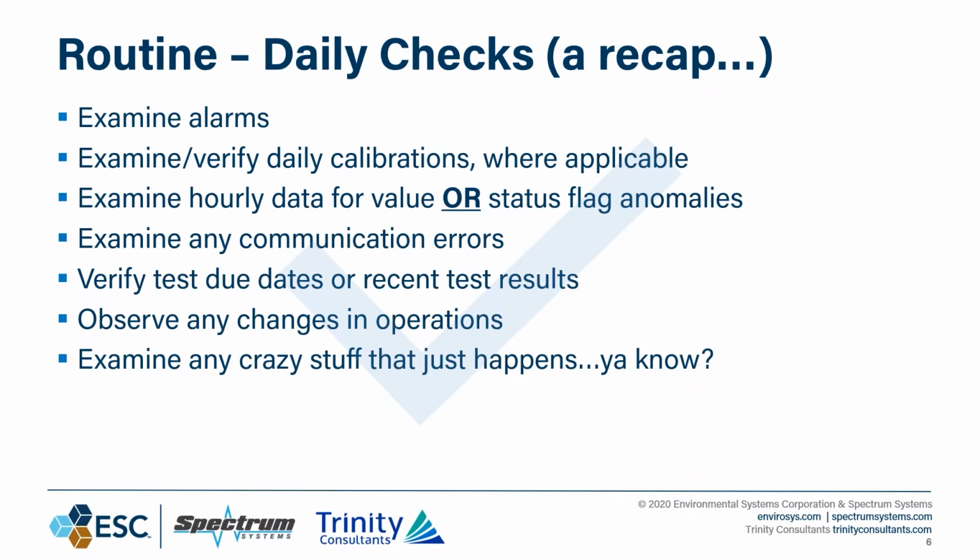Your monitoring plan reflects your QA plan. Your QA plan reflects the maintenance and operation of the system. You should be able to lay your hands on all the components identified in both publications and see that serial numbers match. You should be able to lay hands on them and see that span values match, that maintenance is being done on them on a regular basis, that you have daily and weekly and monthly and quarterly and annual and semi-annual walk down maintenance sheets, whatever was identified in your monitoring plan and QA/QC plan, and perform those like you're supposed to. This makes the fear go away.